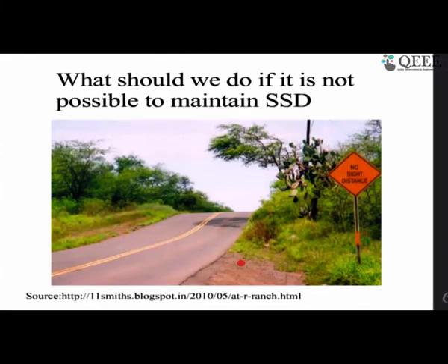So what do we do in this case? If you have an obstructed sight, there are 2 things you can do. Either you can put up this type of sign to warn the driver, and also put up a sign of the reduced speed. The second thing, which is the good thing to do, is to correct and improve this geometry. Once you do that, then you don't need to put this sign. But for temporary purposes, the moment you find out there is a sight distance deficiency, the driver needs to be informed properly, and the safe speed needs to be indicated.